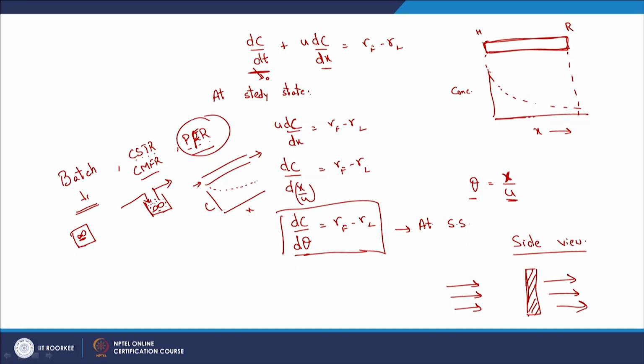As it goes forth, it is still in contact, so what happens? More reactions, or rather, rate of loss. So you are going to observe a decrease in the relevant compound concentration as you go from the face of the reactor to the back of the PRB. In this case, the concentration is changing with distance, and we are assuming uniform flow, one of the fundamental aspects of a plug flow reactor. So your PRB can be modeled by the plug flow reactor. Now, let us try to apply that here.